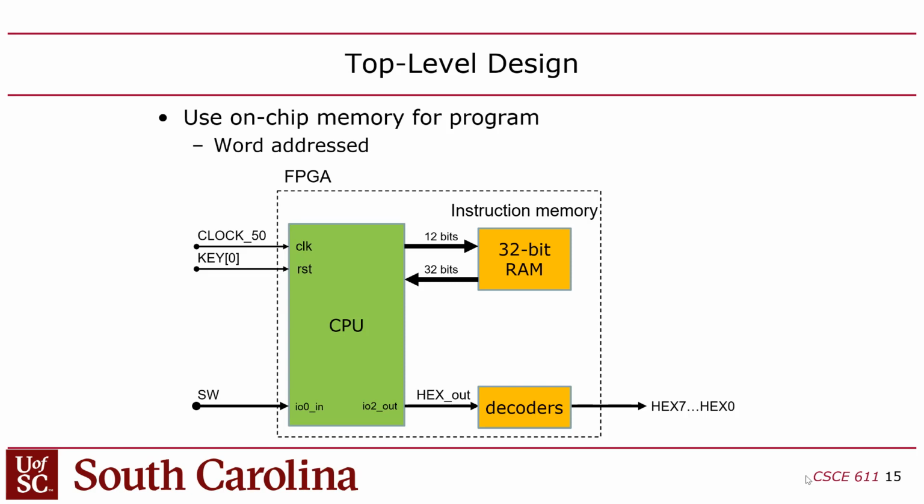So a lot of you will run into this problem, I'm sure, where you compile your design and put it on the FPGA and it's just dead. It's like a paperweight. And you're like, what's going on? Well, chances are, if you look in the resource usage from the compile, it'll say 0 LUTs, 0 RAM, 0 DSPs, right? Because the whole design got optimized out because for some reason there was a breakage in the path from inputs to outputs.